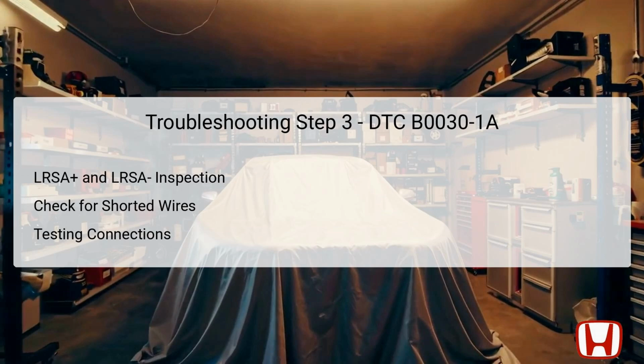Ideal readings should show resistance greater than 1 megaohm, which indicates healthy wiring. If the resistance is lower, it signifies a potential short circuit, which would require locating and repairing the damaged wiring. This step directly analyzes the electrical integrity of the circuits, vital for airbag performance.